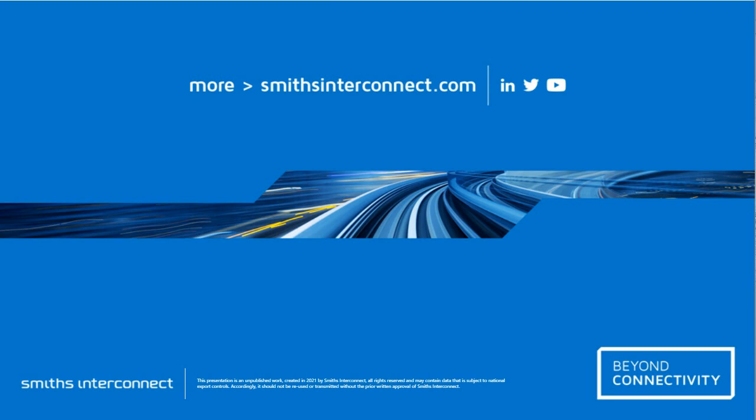The first question is, Kevin and Dennis, do you offer ingress protection or EMI shielding in your interposers? That's a good question, and the answer is yes. We offer both ingress protection and EMI shielding. For ingress protection, we offer gasketed solutions that can pass ingress up to IP67, possibly even higher, depending on how we construct the interposer.